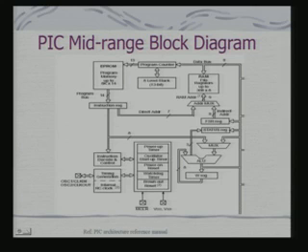So, when the timer finishes its count and it has not been reset, it will generate an interrupt, and that interrupt will enable the system to go back to one of the known predefined states. Okay. So, this watchdog timer is a very important component.